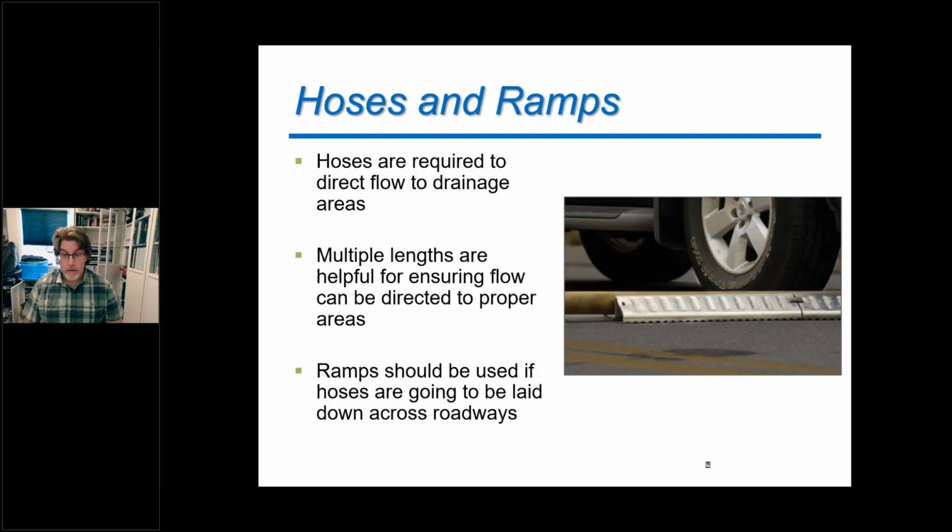Hose ramps, right? If you are going to be running hoses across roadways, you do need to protect those hoses. You should not be allowing people to just drive over hoses while they are flushing. It does create a back pressure wave in your system while that is happening. So if you cannot block off the road for the time that you are doing the flushing, you can order actual hose ramps. Maybe your local fire hall has some that they aren't using anymore. And 2x4s, 2x6s make great little protections for any type of hoses that you are running across the street.